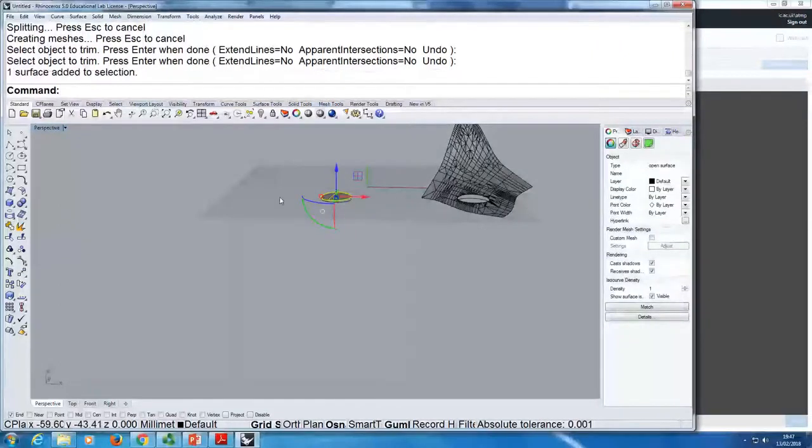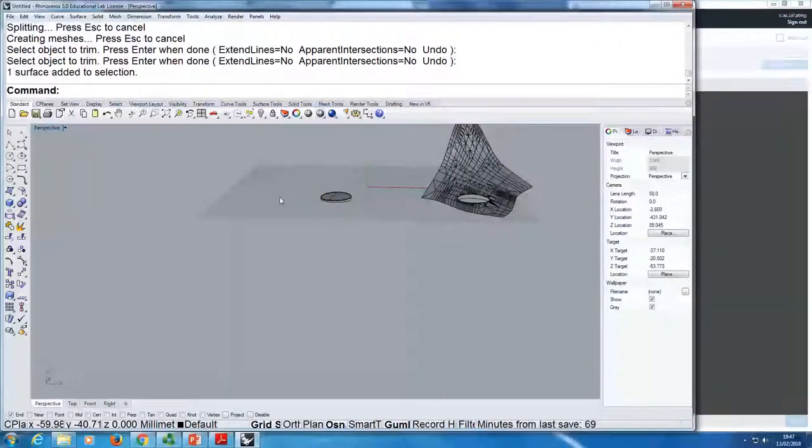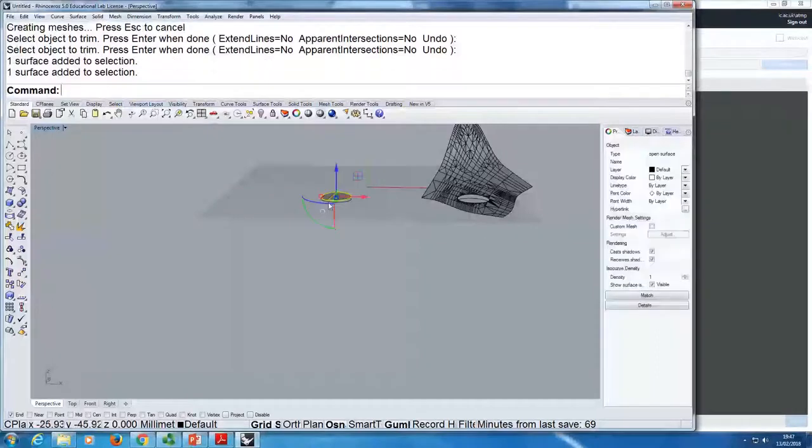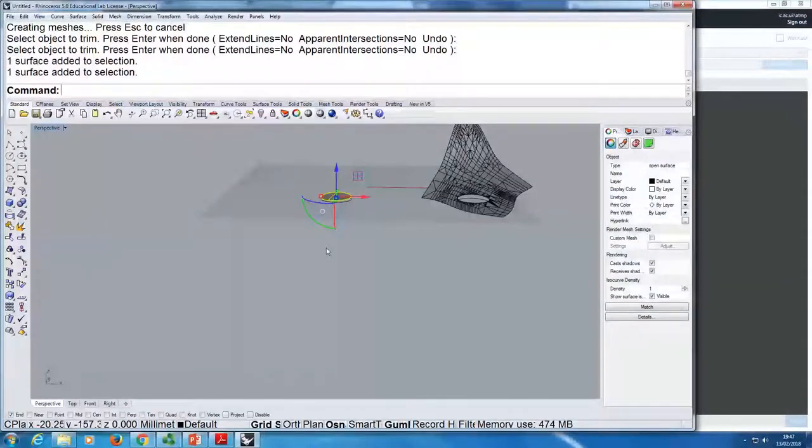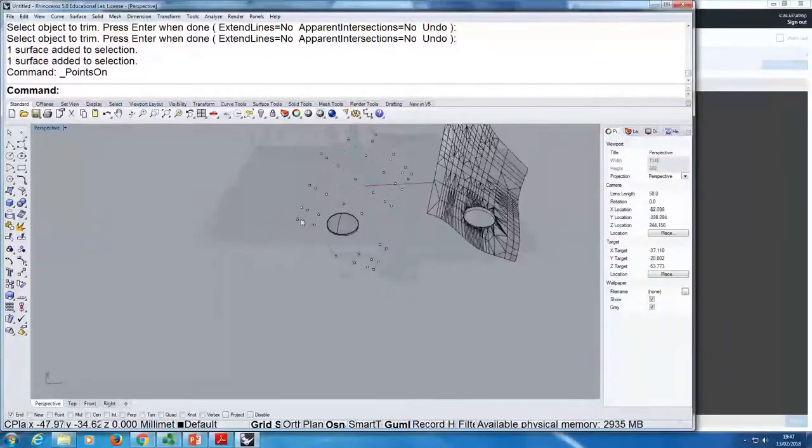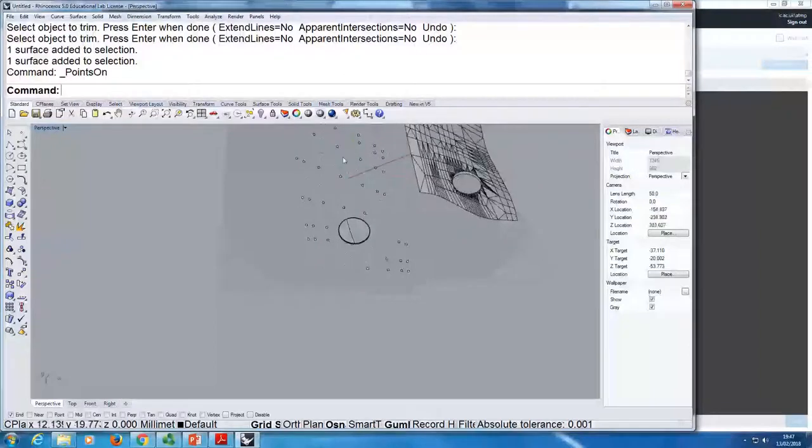Now we end up with that tiny surface, and you might think that's your surface, you're done, you've removed everything else. But actually, if you do F10 or points on, you can see it remembers everything, and that's what makes surfaces very heavy. It has the memory of all of your control points. So here it's easy, right? We have one surface. When you have a stadium, not good to keep all of those control points.